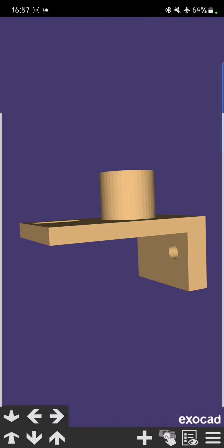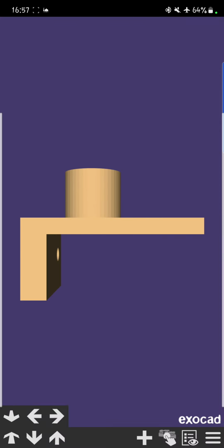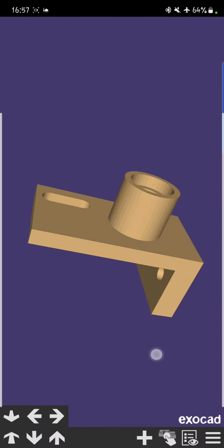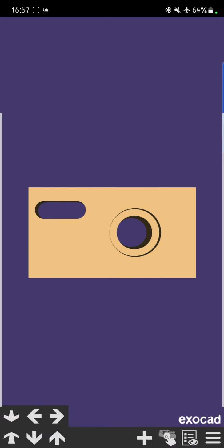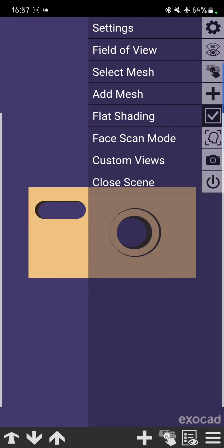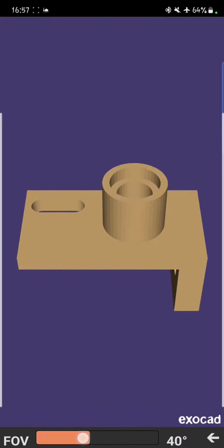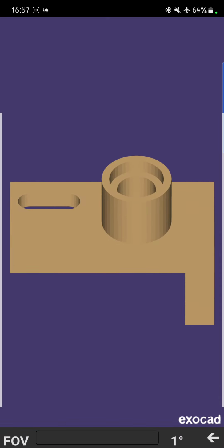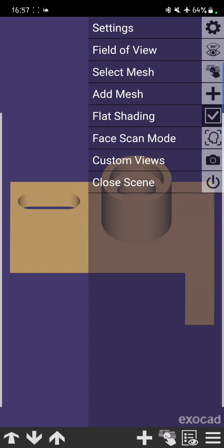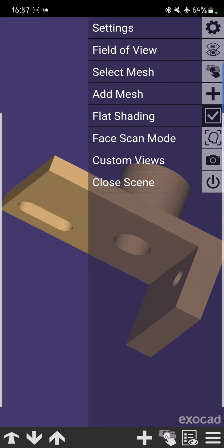If you wanted to see on the top of you, again, you are going to have the same darknesses. Try to show you some parts of the, as you can see here, I see the circle and some part on the inside surface of the circle. So this is not a typical orthographic view. If you wanted to get a typical orthographic view, remember, you have to go here, and then to the second part, a view angle, you put very small, or 0, or 1 in this case, and then exit. So this is how you can use this view.